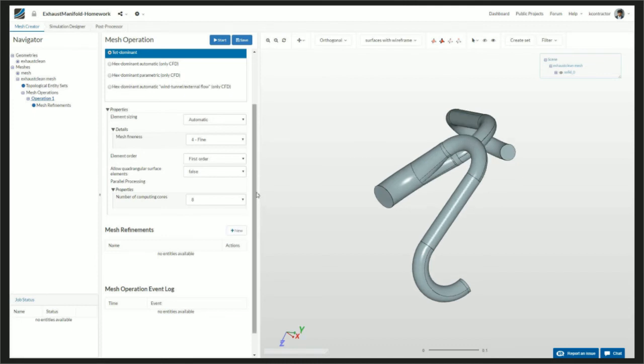As Milad explained earlier, these layers basically refine the boundary layer. And as a general best practice, there is a non-dimensional wall distance called the Y plus. As a general best practice, you need to limit it to 1. But 1 is not so easy to achieve usually. So people usually limit it in a range of 30 to 300 and then use wall functions. So wall functions are basically adapting your solver to a higher value of Y plus. That is what wall functions do. We'll talk a bit more about wall functions in the coming discussion.